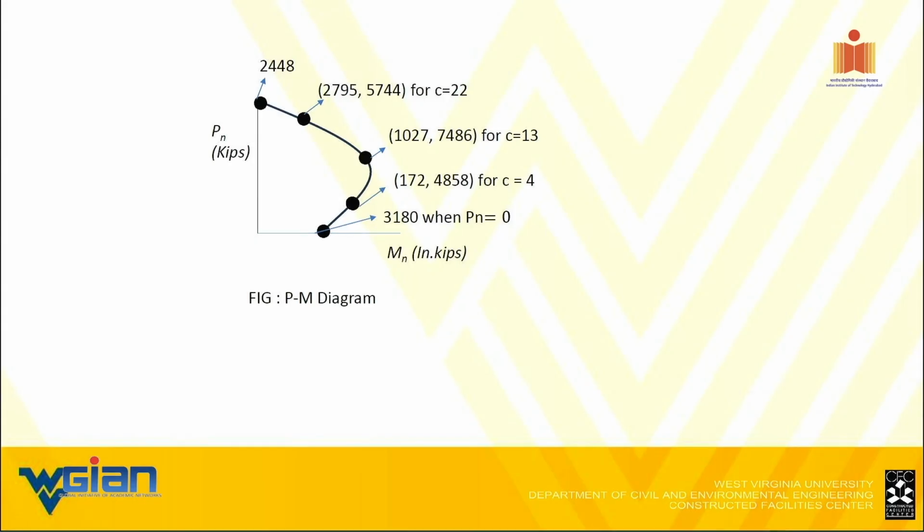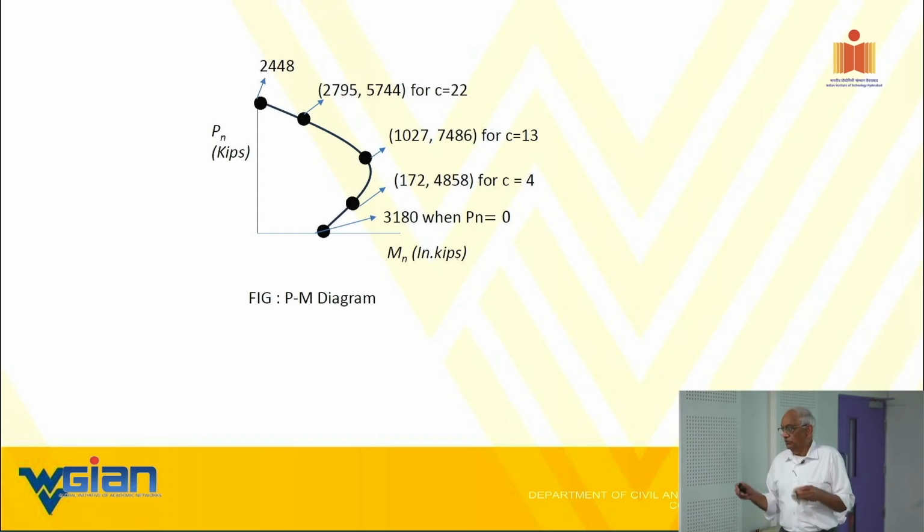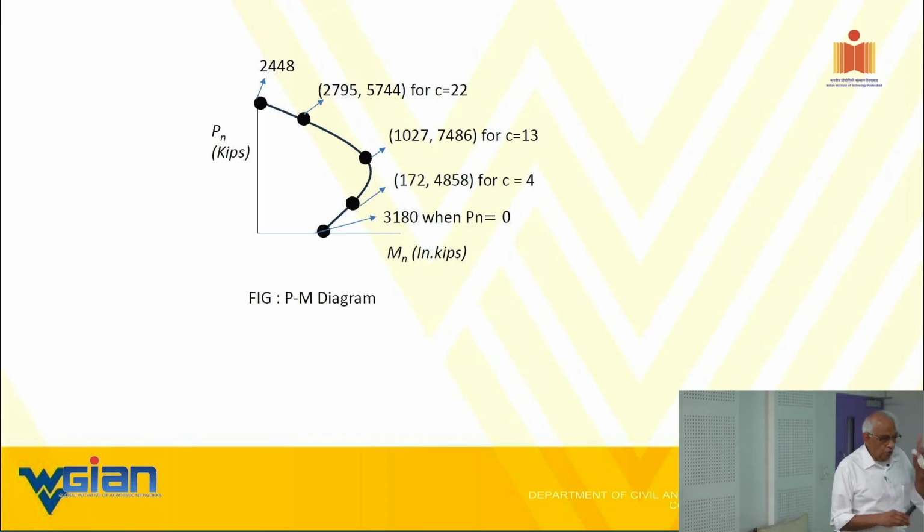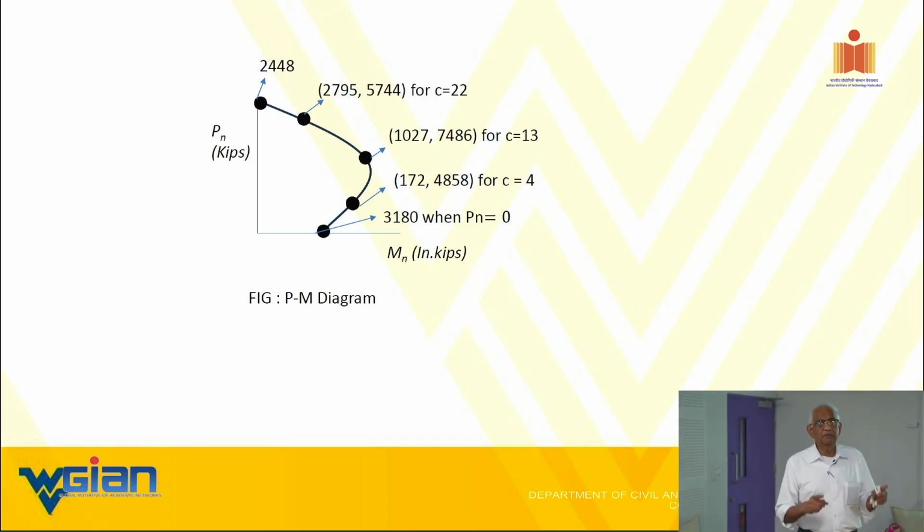All this will be telling you is a lower bound. You are safe. Now, if you want to optimize your design and not spend extra money on extra FRP bars, then you have to justify it. I am taking it as not 0.01, I'm taking minus 0.015 or 0.02, then running the analysis. Why am I taking that? Somebody is going to ask you. I've done 55 tests, I'm always getting 0.02. That's how you do it. The code permits you to do that.